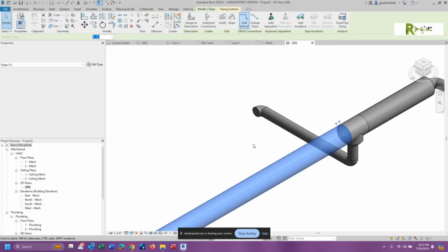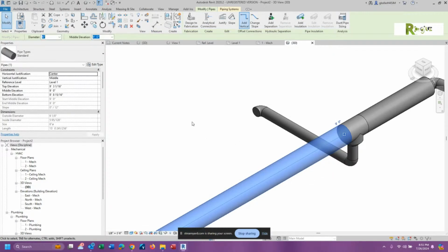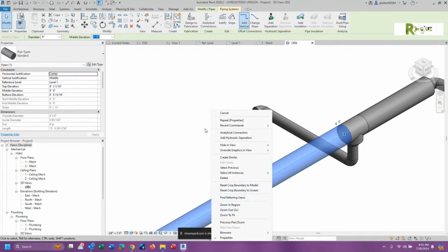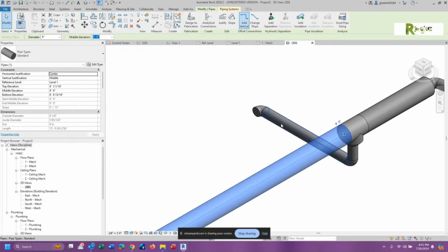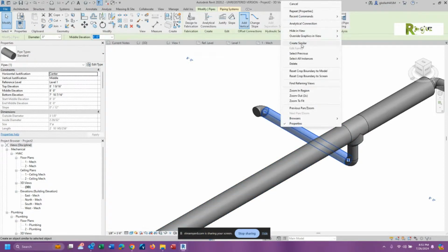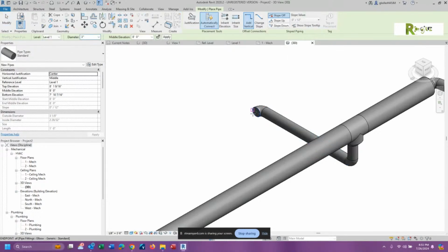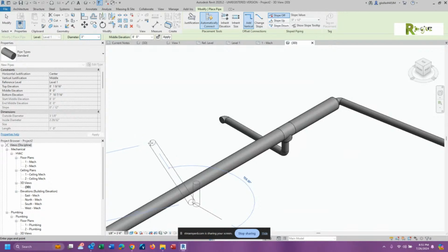And now what you'd find is if you started drawing some more pipe that connected into that, you can do it in here. So pick one of the small pipes and say create similar. Go snap on that big pipe. That'll work there too. And draw. See what it did is it just dropped that 1 foot because you're still drawing at that 8-foot location. And what you're going to see is now you should get a more realistic elbow.